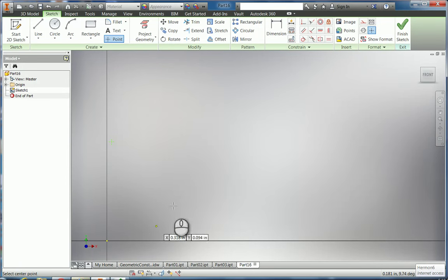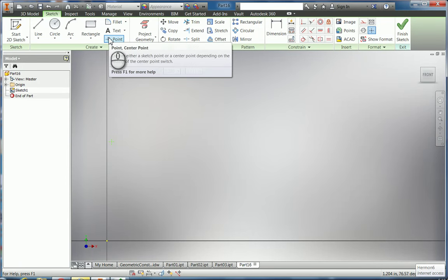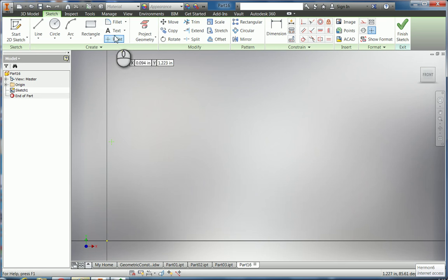Okay, and so now I want to put this other point in here. So I'm going to click another point, and I'm going to see, where do I want that one? I want the vertical distance to be 1. So I'm going to come over here to the Y and put in a 1. And the X would be, again, 3.040 minus 2.550 from the far right side. Return, and there's my next point right there. And then of course I'll go all the way down to my final point, which will be over here.